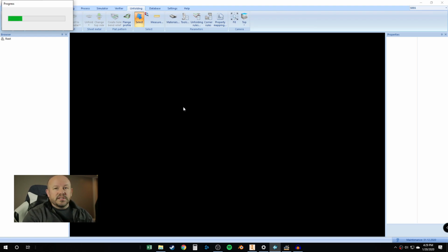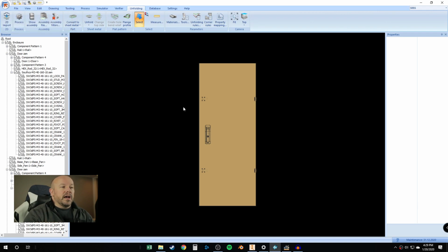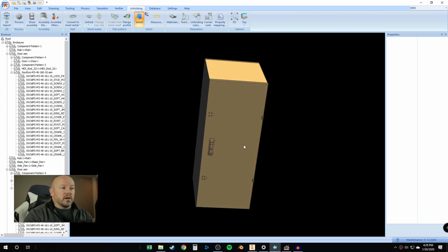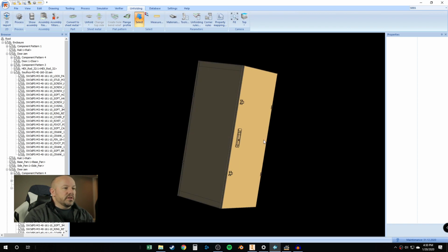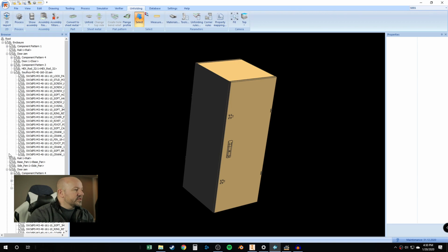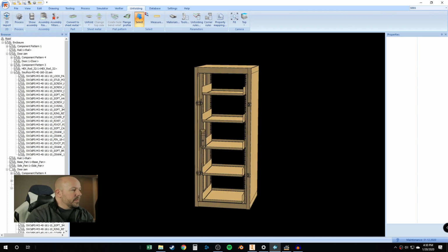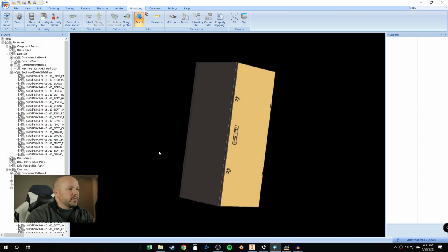And what's nice is that NC Express can read the metadata of all of these solid models and tag that metadata to functions within our software. So we're going to be able to specify the correct material type and functions like we said earlier about turning the part over or not. So here's my enclosure. It's in NC Express. If I turn the door off, for instance, you can see the shelves, etc. are in there. So we'll just check that back on. I've got a full assembly.